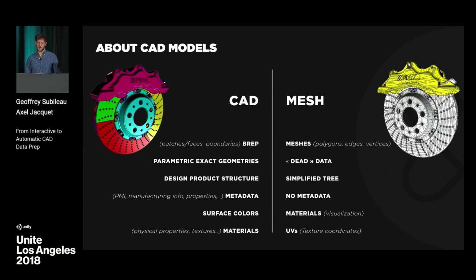A very specific and important thing about CAD models, they are coming from CAD tools like CATIA or Inventor or NX, and basically they contain only parametric, mathematically defined surfaces. And these surfaces need to be translated into light meshes that can be handled by a game engine like Unity. And that's precisely what Pyxis solutions do.